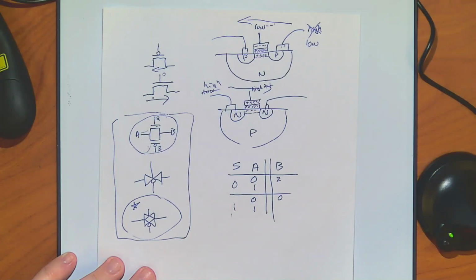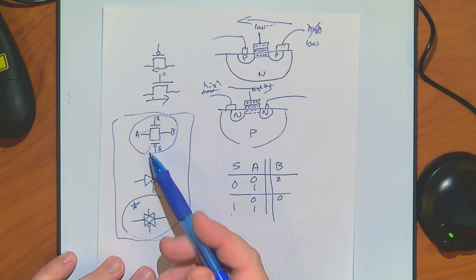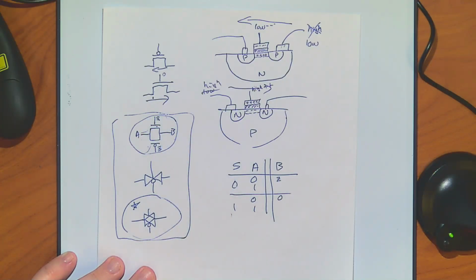And we're just going to specify you need to do this. It must be S bar, because we want both gates on at the same time. That's the whole point of this. We're only giving you both gates, so one carries power well, one carries ground well, so you get a really good transmission of the two. So you have to invert them. It goes so far that on some of these, instead of giving you both controls, they'll just hook an inverter there and only give you one.